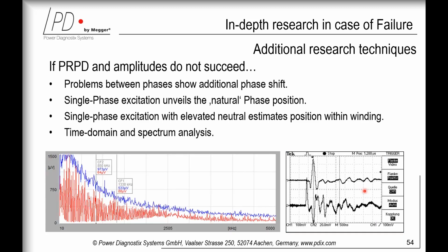Additional research in the time domain can give valuable information about the transmission path. With respect to the influence of impedance changes and so on during the travel path, a signal traveling along a conductor is rather sharp and clean, here shown in the first graph, while a radiated signal, which is picked up somewhere, is usually more strongly oscillating.